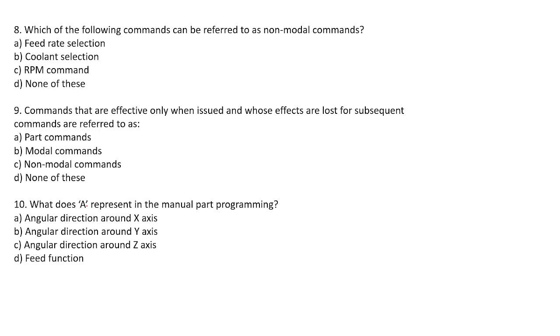The tool locations are specified with respect to these zeros that we fix, which is called the fixed zero, or world coordinate system. Another point is the floating zero, which follows the user coordinate system or work coordinate system, whatever we say. The code follows those coordinates and operates at zero points in any position of the machine table.